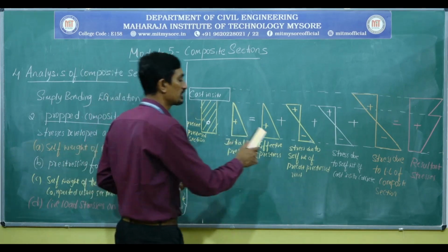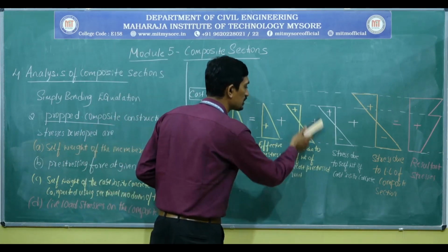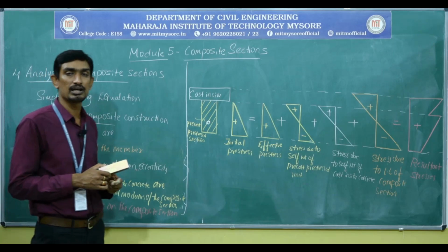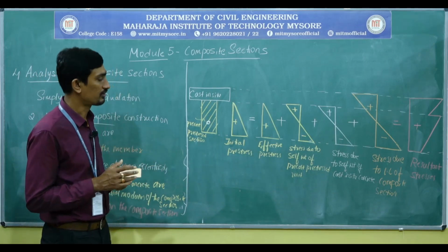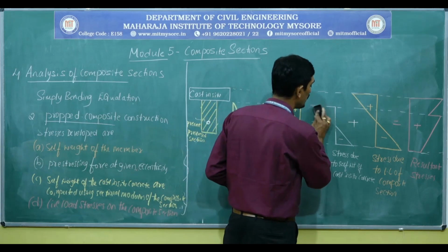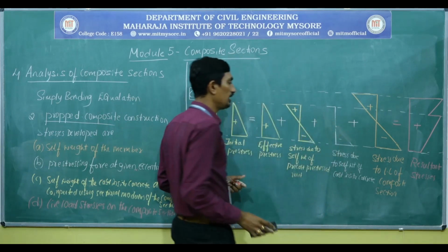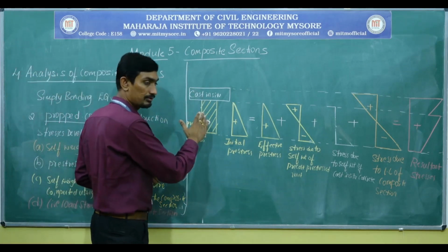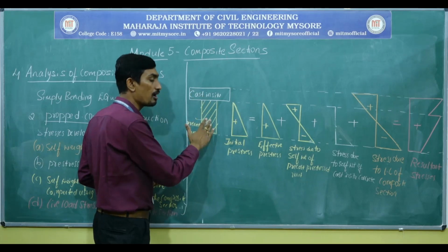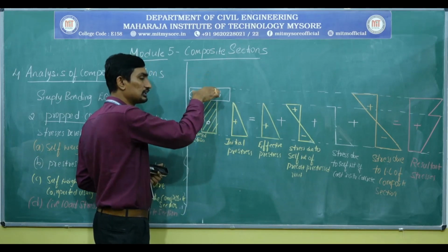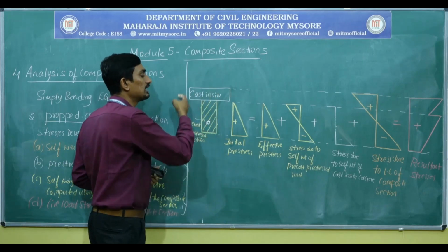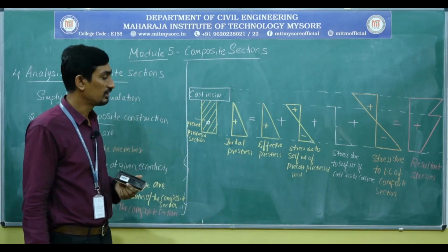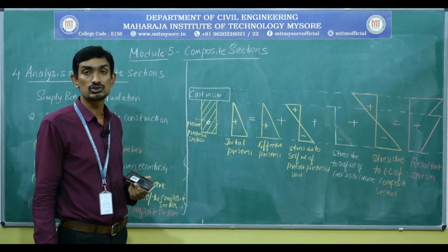Next, stresses due to the self-weight of the precast pre-stressed unit, no change in this, as I stated. Next, the change in this particular thing is, as I stated, since the precast pre-stressed unit is propped while placing the cast in situ concrete slab, I am going to consider the entire composite section in order to assess the stresses due to the self-weight of the cast in situ concrete.